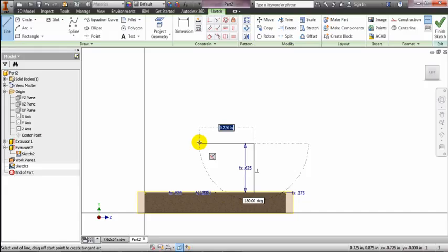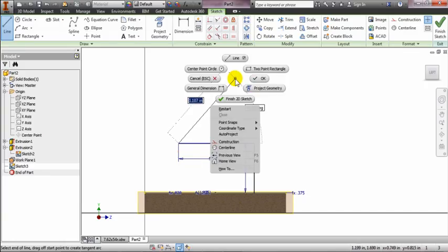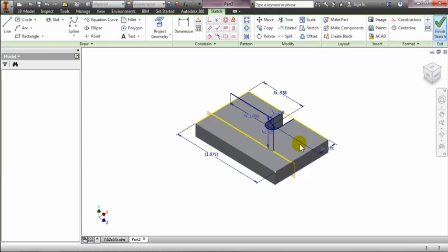So there's a lot of different ways that I can do this, but I'm going to do it by using a function, because I want all these to be parametric equations. So I'm going to do D0 times 4. Because my original dimension, D0, was 0.25, so I'm just going to do it times 4. And so now I've got my line coming out to this area. Now I'm going to right click and cancel, and I'm going to go to Finish Sketch.